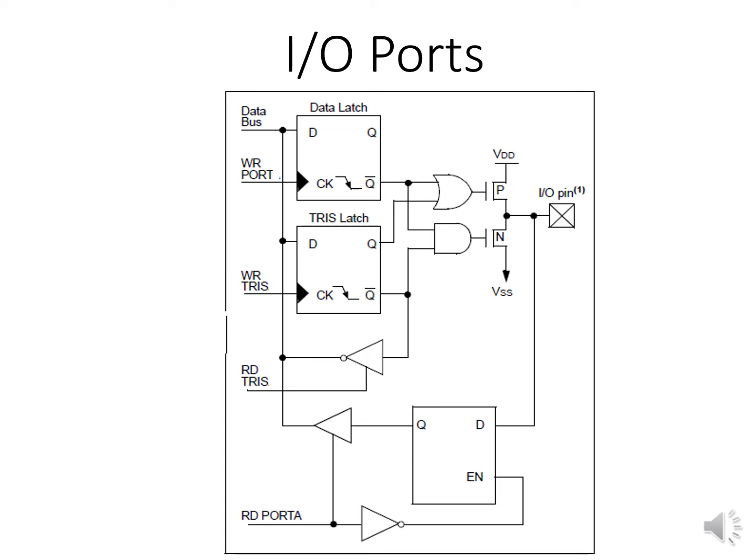For those output devices that need more than 25 milliamps, the port pin can be made to switch some switching circuit, such as a transistor switch or a relay circuit. In some cases, the port pin can switch a transistor switch, and the transistor switch in turn switches a relay circuit.